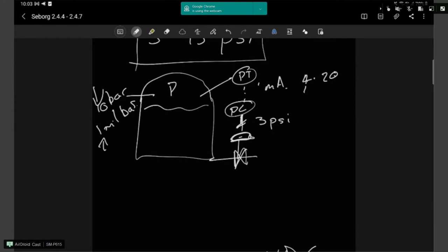Because of this circumference of the area of the diaphragm portion, the air supplied to it can provide a greater force for the valve to open and close, meaning that you can operate the valve at higher process conditions or process pressures. So the diaphragm pressure doesn't matter. It's basically just the physical configuration or setup of that valve, how that changes.